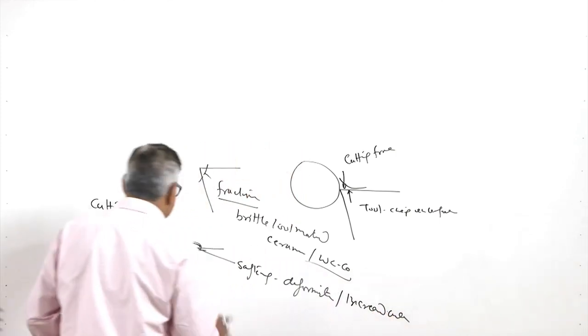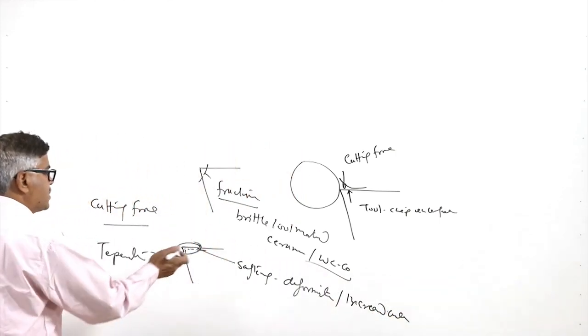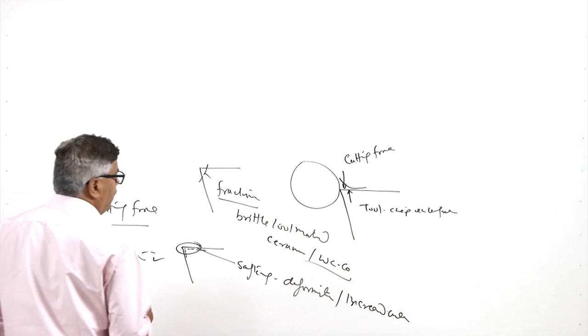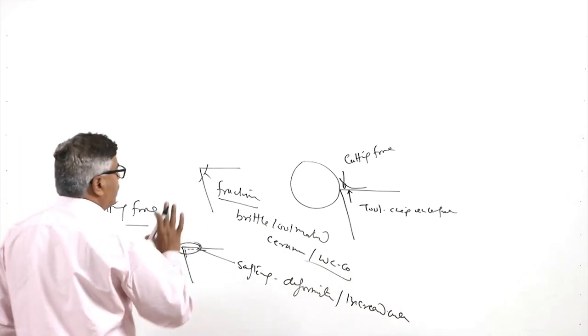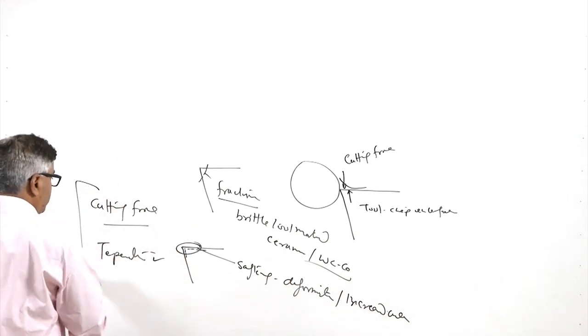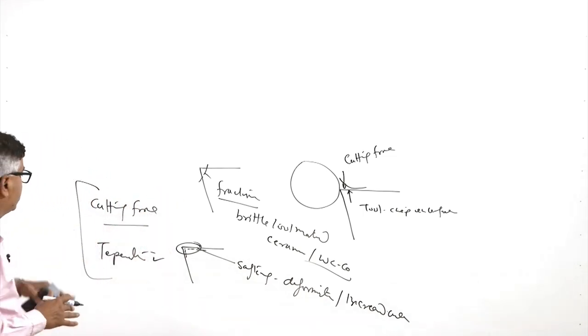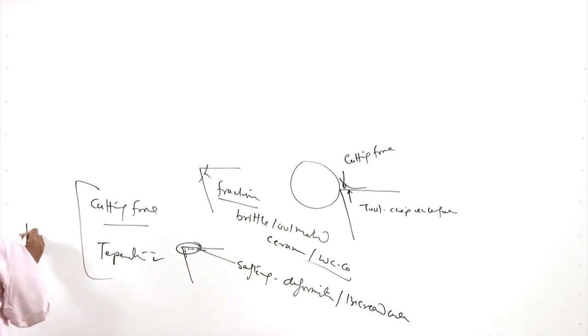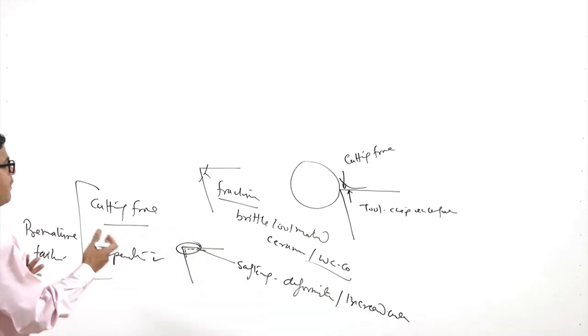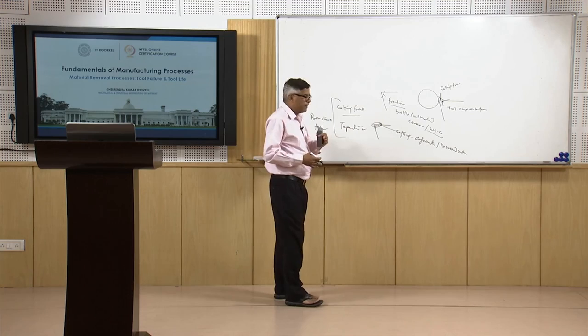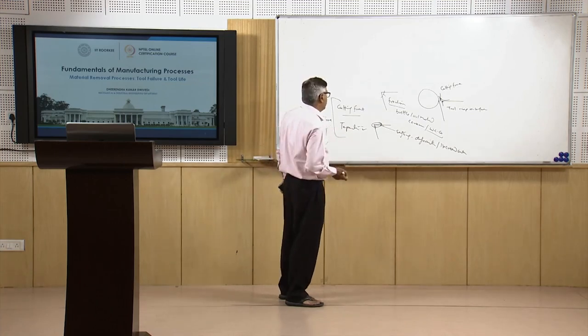Basically the blunting of the cutting edge due to softening is the main way by which failure of the tool occurs. So, if cutting forces or temperature rise are too much, it leads to premature failure of the tool, like sudden fracture of the cutting edge or blunting of the cutting edge due to softening.